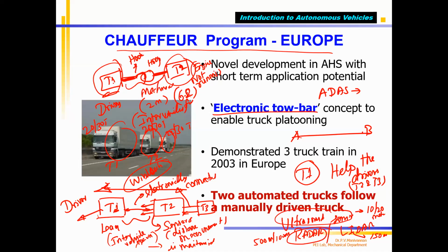to 500 meters. Correct? So they can use this, but for measuring inter-vehicle spacing, you don't need to go for radar, LiDAR, all those things, which are expensive. You can use an ultrasound sensor, which costs 1,000 rupees or maybe $10, $20, something like that, which can measure. Okay, that's how it is done.